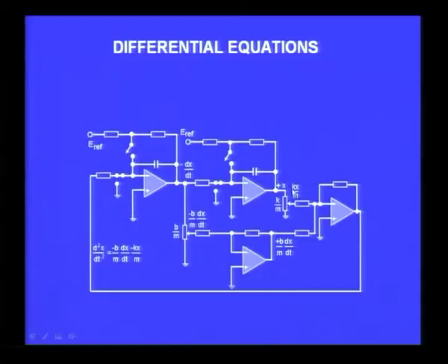Then you provide the corresponding k by m x proportionality here, and here what you have done is the dx by dt is multiplied by a proportionality constant minus b by m using this potentiometer, and that output is just inverted because this is minus, here this will become plus, and these two terms are now added, and that is what d square x by dt square is. So, that is given at the input here. So, you find this becomes a consistent circuit